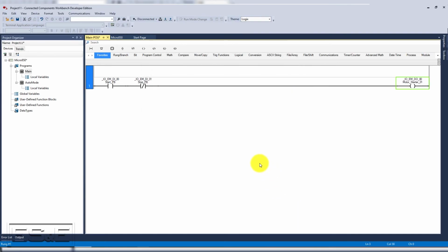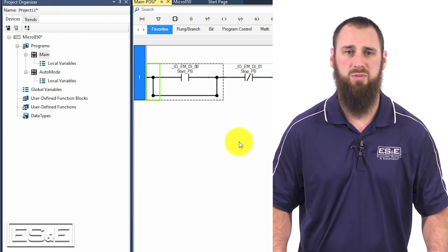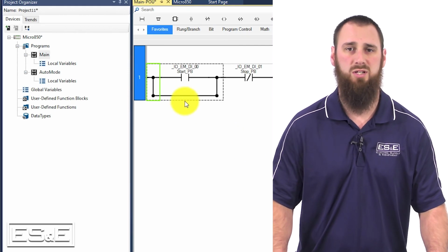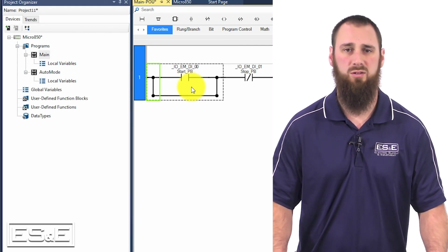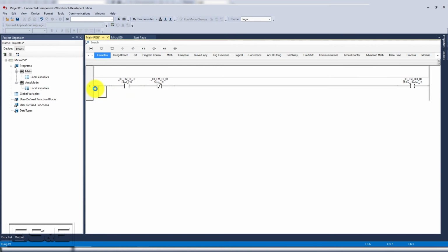So now we go back to the beginning of the rung where we need to add a branch. We'll drag that down, and a cautionary word about branches. If you don't drop the branch in the correct place on the rung, it is very difficult to reposition the branch, so it is much easier to delete it and then place a new branch in the correct location. Last, we will add the latching circuit portion on the new branch. It did not go in the correct place, so we'll drag it, or you can do a copy paste.